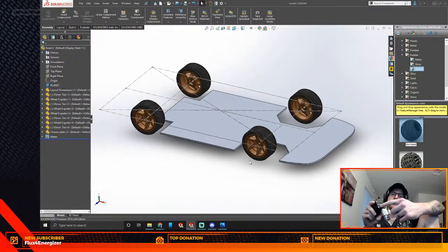There is an E3D style adapter that this BMG clone connects to, and that is threaded onto a hollow piece of M6, which goes down in here, and it locks everything in place and has the PTFE tube going down only till about right here.